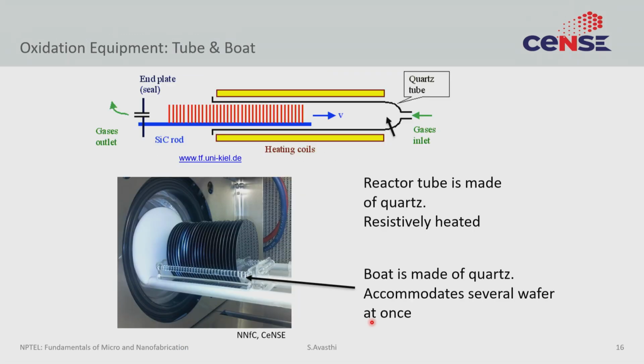This is a little more detail into how exactly all of this happens. Because you are so sensitive to purity and contamination is such a huge deal, this is the most sensitive step. You want your gate oxidation to be absolutely pure. So, you try very hard to remove any source of contamination or any source of irreproducibility. Anything that cannot be controlled must either be removed or controlled.